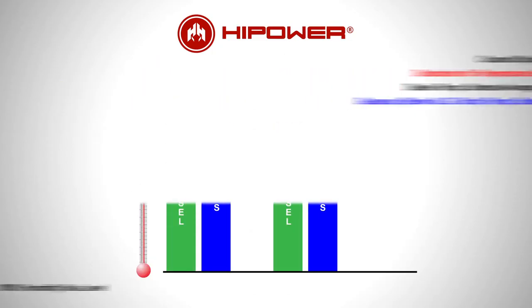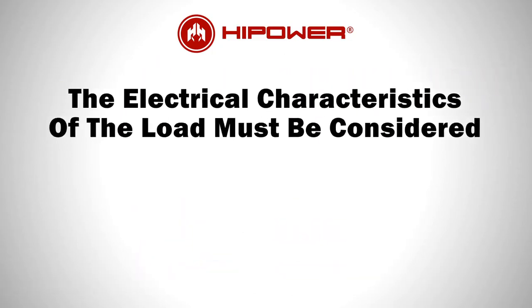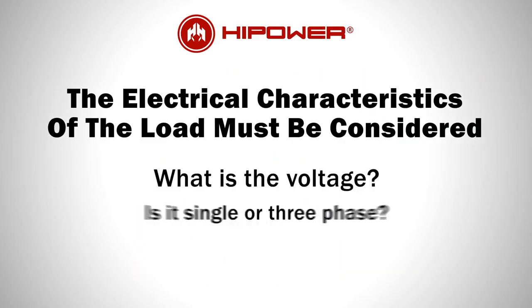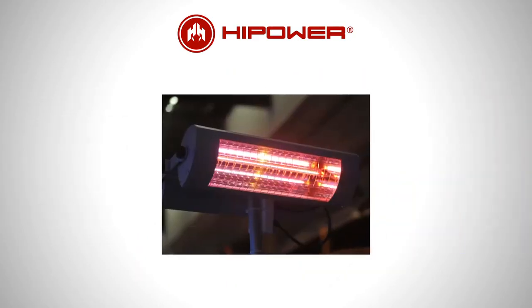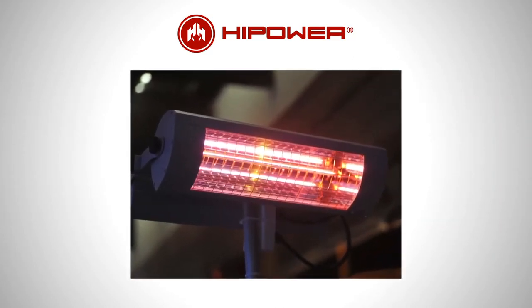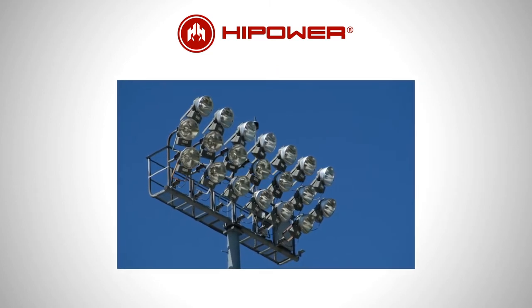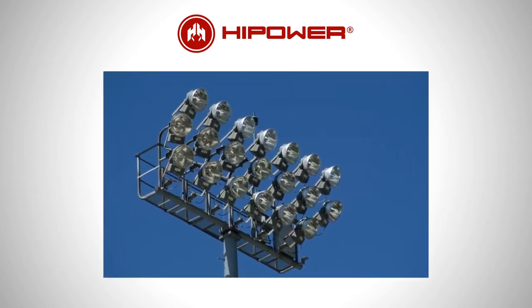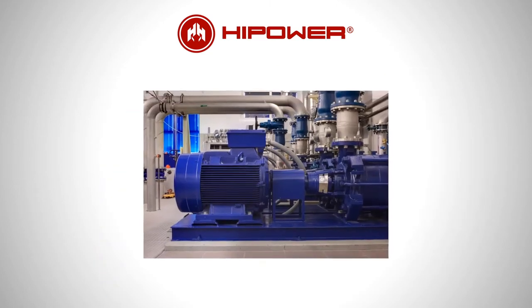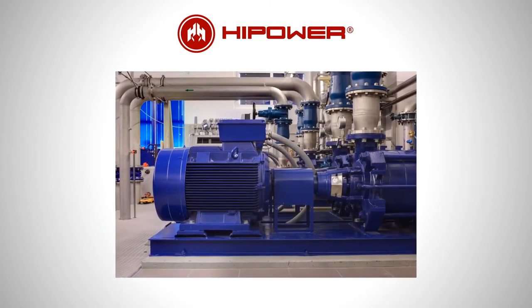Having determined any duration, the electrical characteristics of the load have to be taken into account, such as what is the voltage? Is it single or three-phase? Having determined the load characteristics, all the kilowatts of the various loads have to be totaled. Purely reactive or non-reactive loads, such as lights and heating, can be just totaled by adding up their power ratings. For reactive loads, such as electric motors, you have to take into account the additional power required on starting.